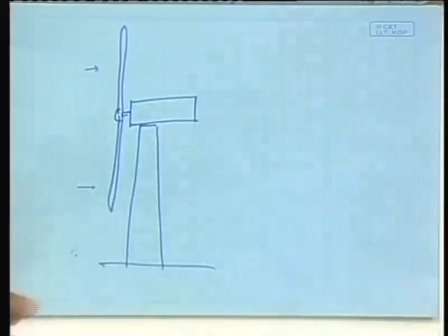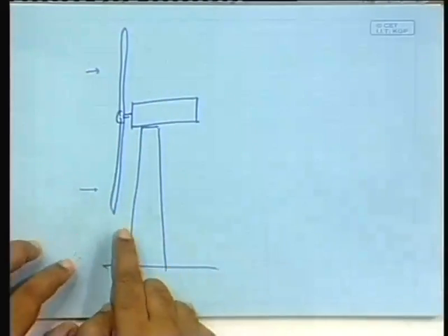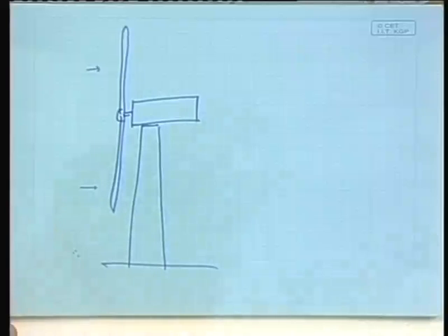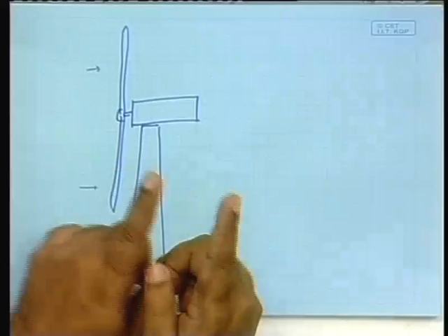As a result, the torque will pulsate as it goes through the whole cycle, and that torque pulsation obviously will be less if you have a 3-bladed turbine. Why? Because there are 2 blades that are not undergoing that reduction in the torque, only one blade is undergoing the reduction in torque. So, the total reduction or the fluctuation, the pulsation will be less felt by a 3-bladed turbine than a 2-bladed turbine.